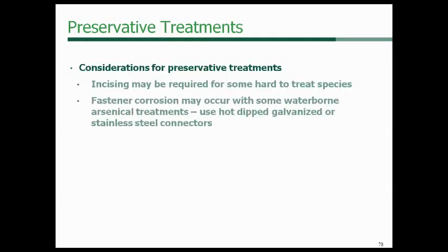So as I mentioned, incising for hard-to-treat species, as I always like to point out with treated lumber, some of the newer treatments have been shown to corrode untreated fasteners, so you'll want to use either a hot-dipped galvanized or a stainless steel connector if you're using treated lumber.